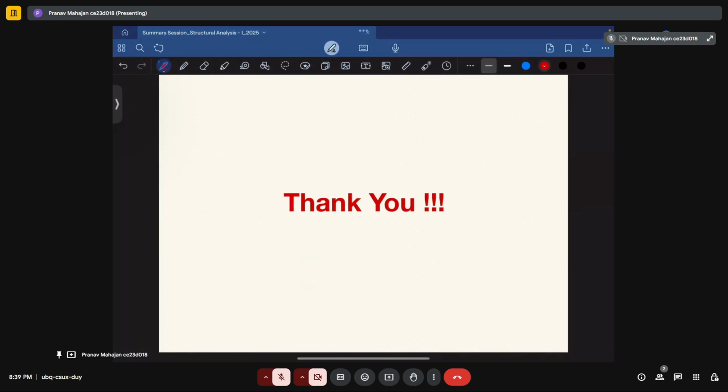Your fixed support will become a free support, and your free support will become a fixed support. Then your bending moment diagram will become the loading diagram for the conjugate beam. When you calculate the shear of the conjugate beam, you will get the value of slope at that particular point. And when you calculate the bending moment of the conjugate beam, that will become the deflection in the real beam. So these are the two basic things that you will use in the conjugate beam method.